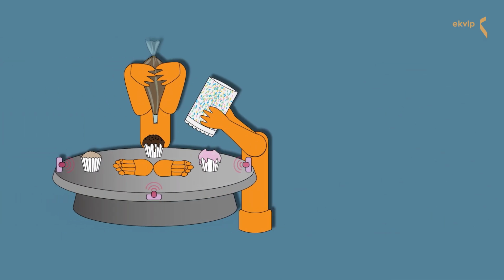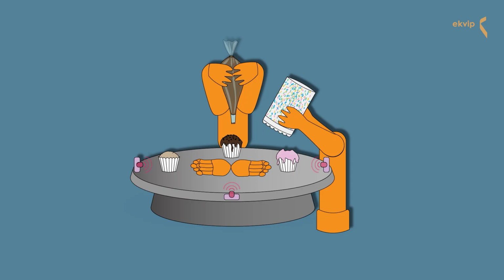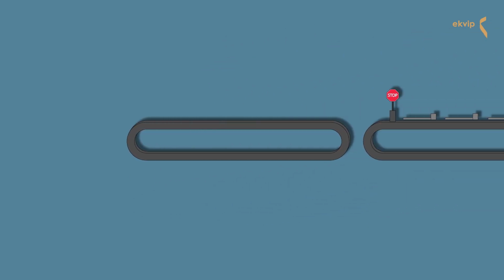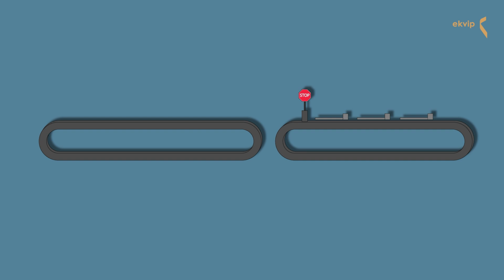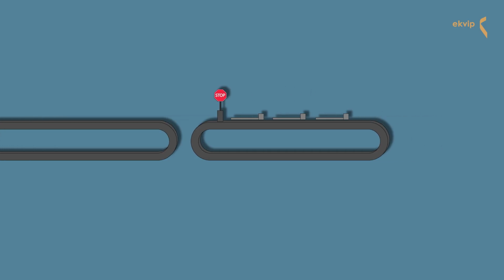The turntable is a drive, and above each of its 4 positions, drop-off, glazing, topping, and exit, there is a sensor indicating whether the station is occupied. The glazing and topping stations consist of a simple drive and a pusher. The exit station uses a cylinder. The conveyor belts are simple drives. The stoppers are cylinders. The transfer units are lift transfer units.